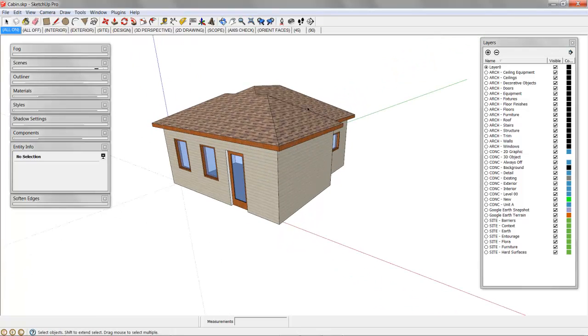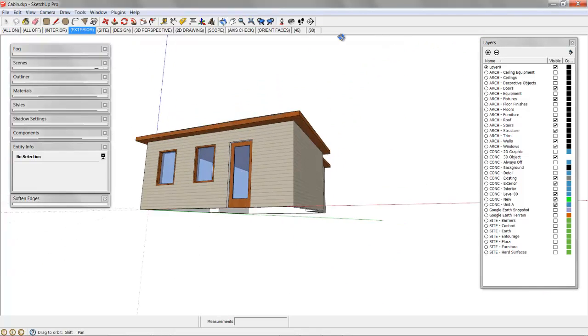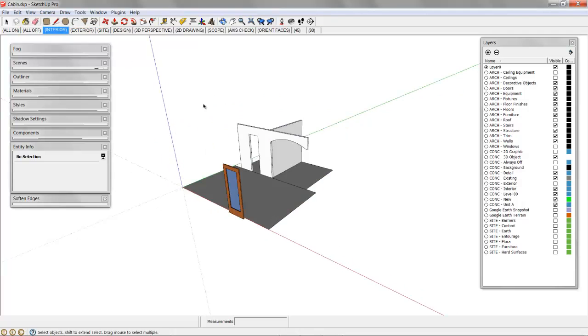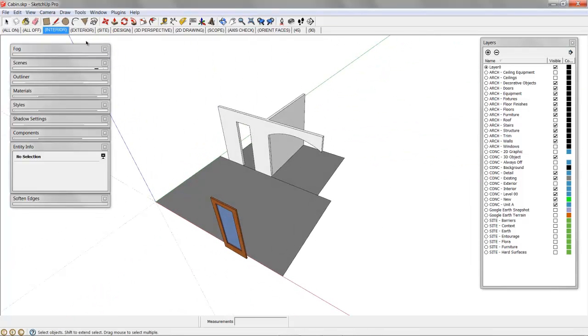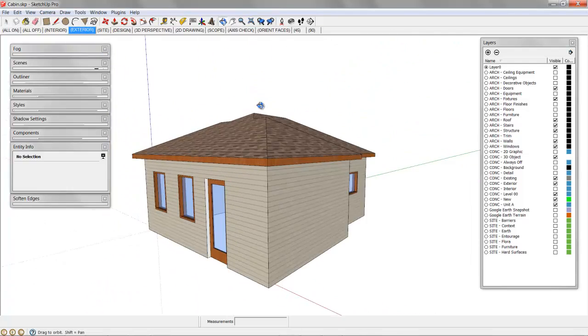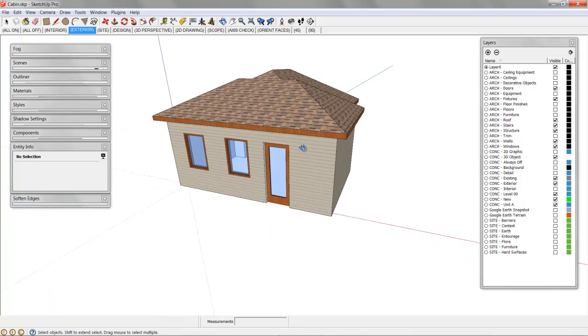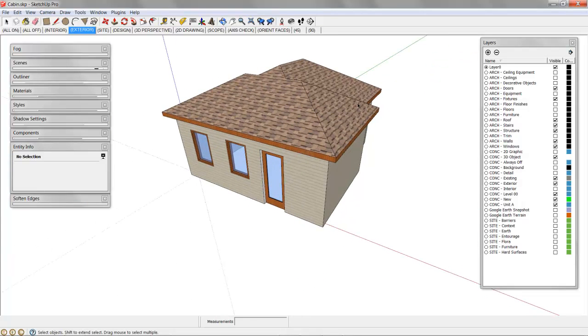So check that out. If I unhide everything, now we can look at our interior, we can look at our exterior, and you can go all on, off. Site is not quite set up, but that's a really slick tool to have, so you can work on the inside of your model and then work on the outside of the model. And you can see how the interior walls are turned off, floors are turned off. Those layer states are definitely adjustable, but they're already set up for you.